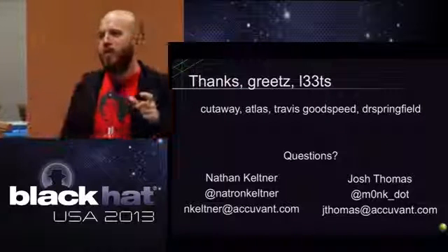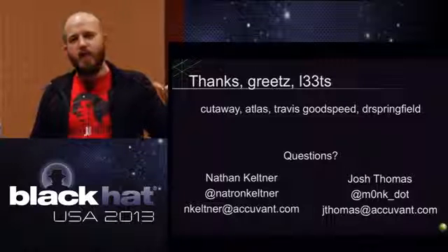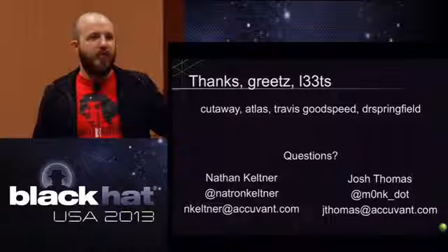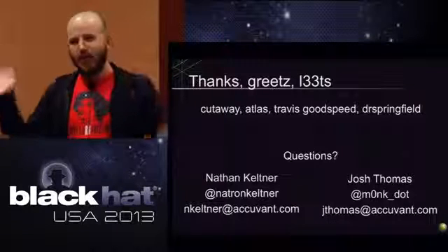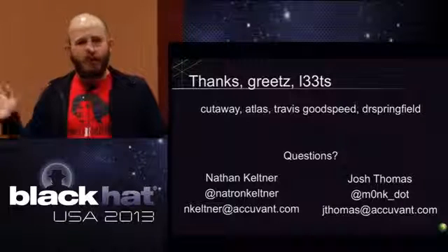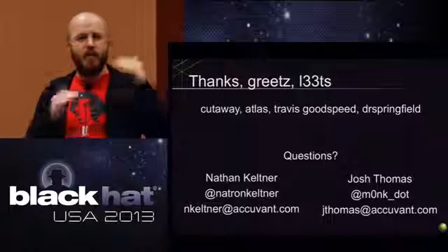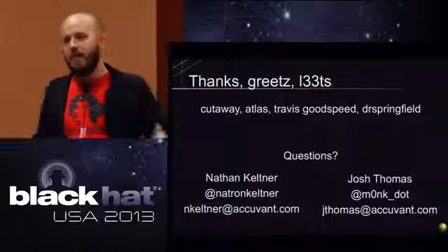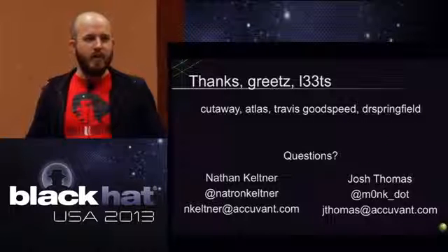And finally, in one place, you find a remark from the author that says, because of normal electromagnetic interference, like in storms and whatever else, the execution pointer gets corrupted all the time. So just in normal usage of the thing, the instruction pointer will jump someplace else and then go all crazy. And it's okay because there's a hardware watchdog paying attention that will reset it if it gets too out of whack. That's not a big deal for that. But it points out a funny aside: they had to put all these checks in because they wanted to make sure the execution pointer didn't accidentally get corrupted by a lightning bolt or whatever and then jump into the flash overwrite section and corrupt the whole world, and then it'd be bricked forever. That would be really bad.